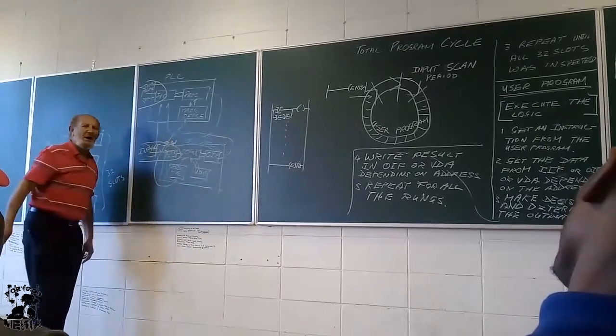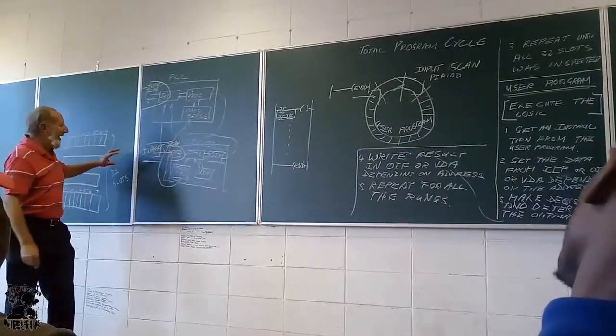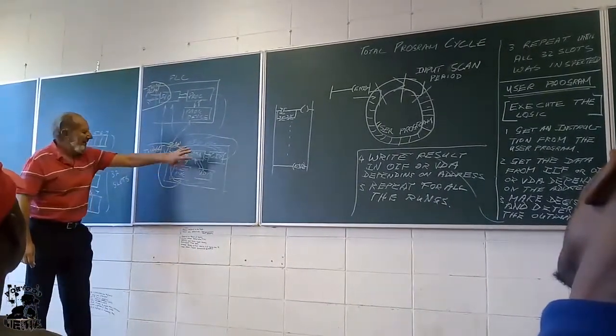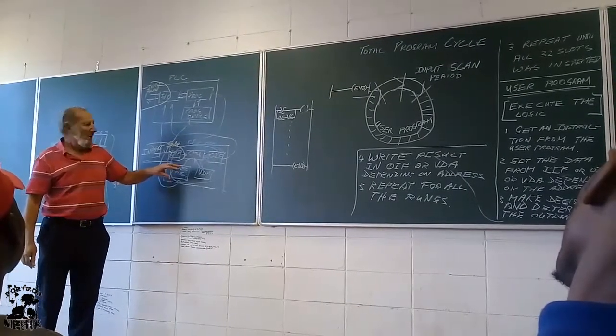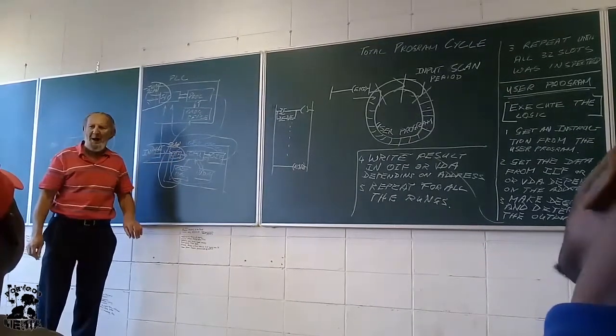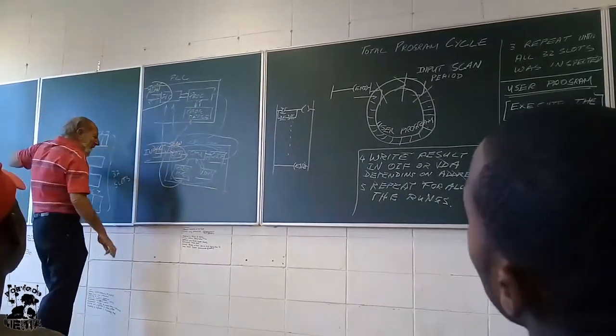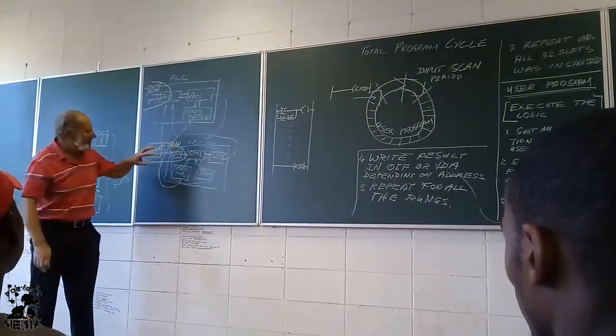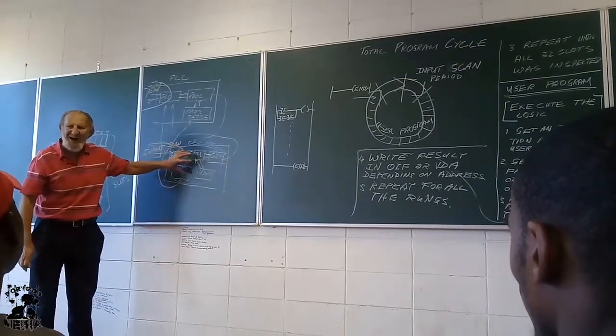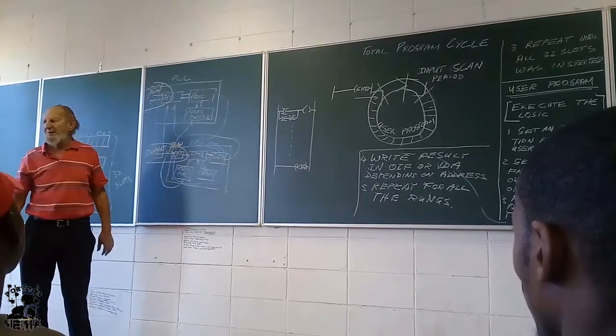While it's doing the input scan, the CPU is not doing anything else. When it's doing the user program, it is not seeing the inputs, it's not seeing the outputs. It's performing the logic just in the processor.